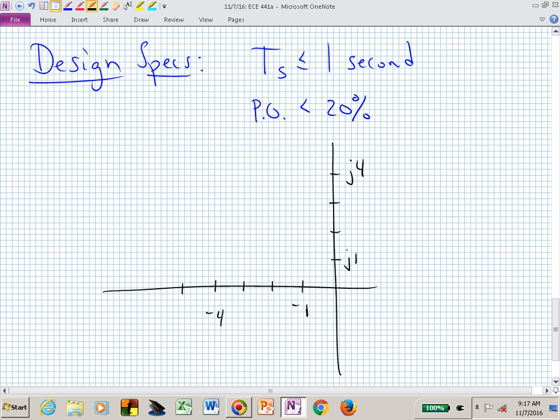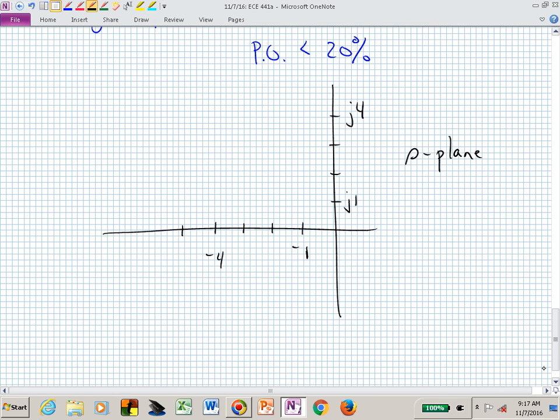What's a 1% settling time give us? So here is our S-plane, and if I say settling time, what do you see? Okay, now we're seeing hypotenuse, we're seeing root loci. Now if I say settling time, what do you start imagining mentally? Yes, I see somebody doing this. So now it's a vertical line, isn't it? But that vertical line is basically somewhere located, usually in the left half plane, to give us a particular speed of response for settling time.